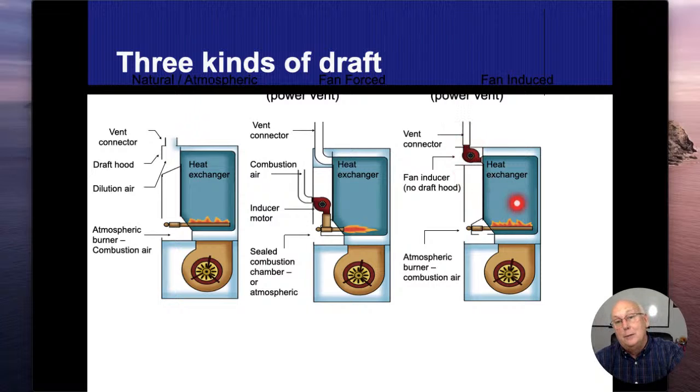So now, even though it's a smaller fan and not as powerful as our blower fan, when that burner kicks on and the inducer is going and it creates a negative pressure in there, at least if there is an opening, we're going to have that secondary safety thing where air is going to come into the heat exchanger and not into the circulation air. And then if I have a positive pressure when the blower fan's going, that makes it an even stronger pressure differential. So the less likely of a chance that comes in there.